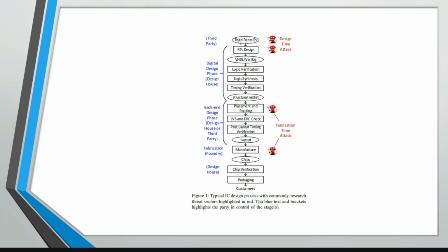So the designer will start discussing and come to a conclusion on what can be done and what cannot be. Both agree on what can be done and how much duration it needs to design this particular IC proposal. Then they start giving it to the RTL design engineers. RTL design engineers are the first engineers who will start writing the code using Verilog or VHDL.